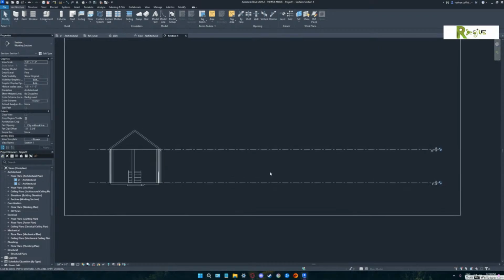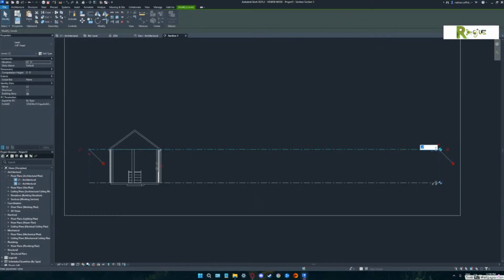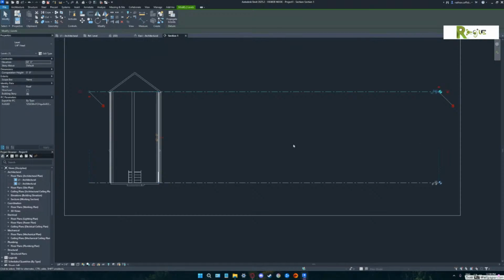you would see we have 2 levels. I want you to rename L2 to be the roof. Type in roof. Perfect. And I want you to make that 60 feet. What you're going to see is now our job is going to go from a little 1-story building. We're going to now make it a high rise, a 60-foot building, 5 stories. All right. So the next thing you would typically do is you could draw, if you go back to